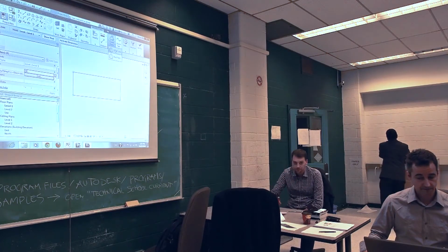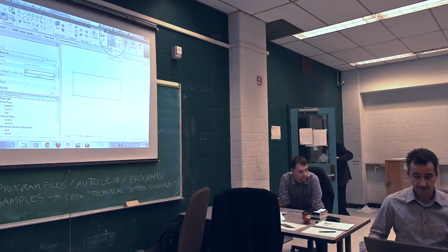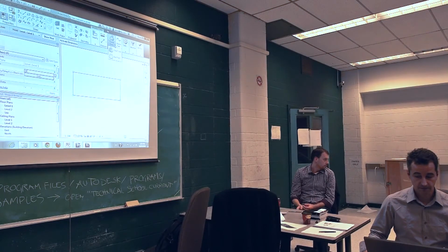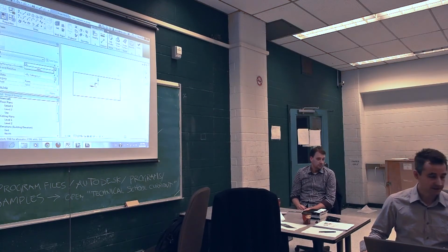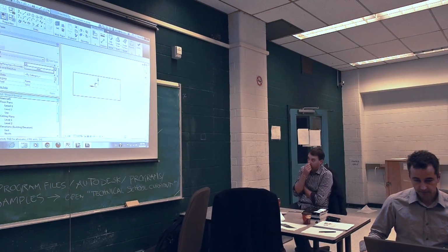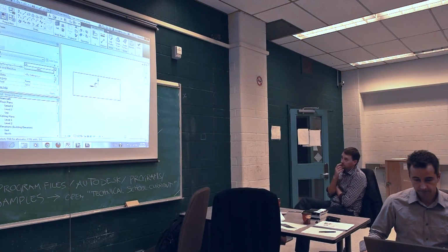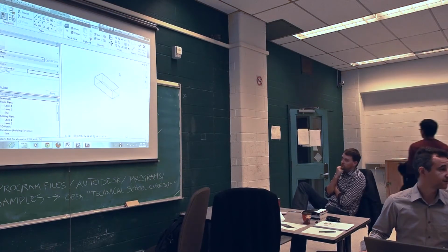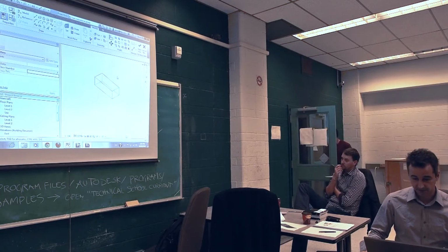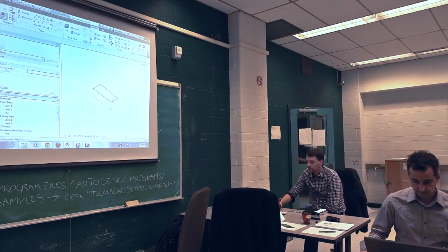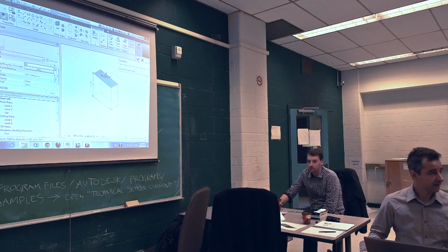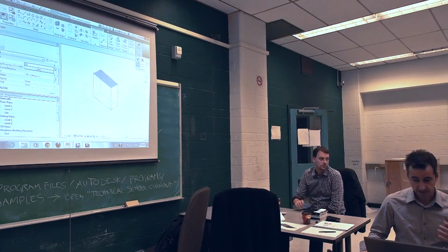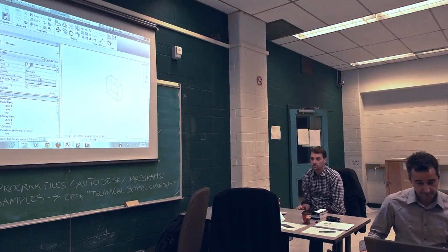And then Create Form, sorry. In here you have Create Form, with a drop-down menu. Choose Solid Form. You did this, and you have a 3D mass. If I look in 3D, this is my building, believe it or not. Probably not, but this is my building. Finish Mass will just end the editing. So if I finish this, now I have my building, right?